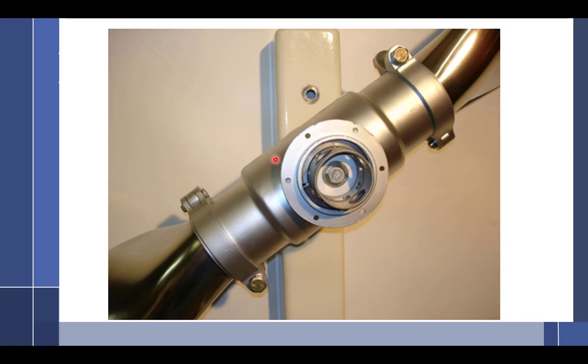All right, ground adjustable props. So this is something that you'll have an opportunity to actually adjust. You can adjust each blade on the ground. You don't try it in the air. If you do, give me a call. I want to watch. So you just undo these clamps right here, down there, and the blades will rotate quite easily. And so you'll do that.